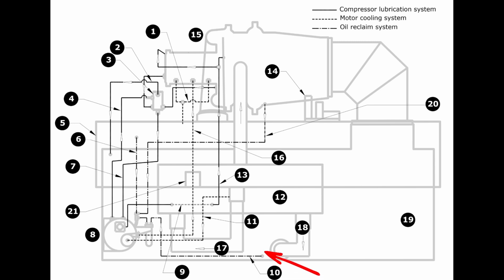Like what Train suggests, from fully closed, they should be anywhere from a quarter of a turn to 2 turns open. Most of the time you'll go 1 to 2 full turns, but no more than 2 turns, one turn being a complete 360-degree rotation of the stem of the valve. So no more than 2 turns out on this line. Anything more than that, then you will start to overfeed this line, and you're going to cause issues with your eductor system and your oil tank being able to maintain properly.